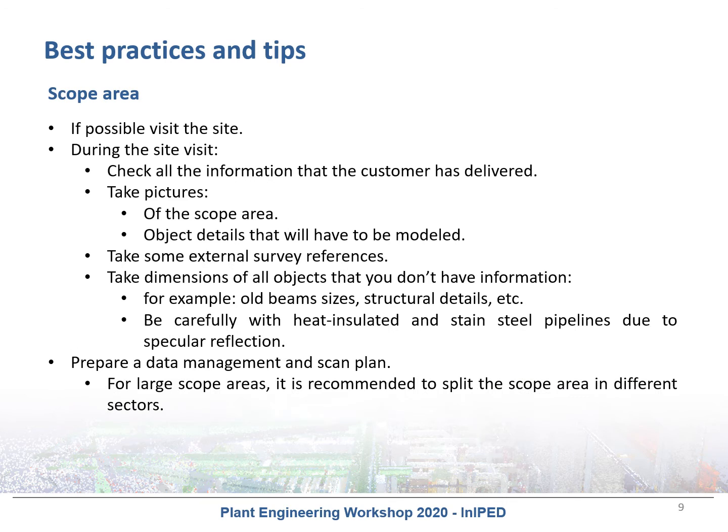Normally, the laser captures are performed by an external company. An important issue is in case you have to be present on the day the scan captures are made. Why is it important? Because you have to do a parallel work while the scans are done. You must agree with the external company on some external survey reference. Also, you must check all the information that the customer delivered and take notes on the differences encountered.